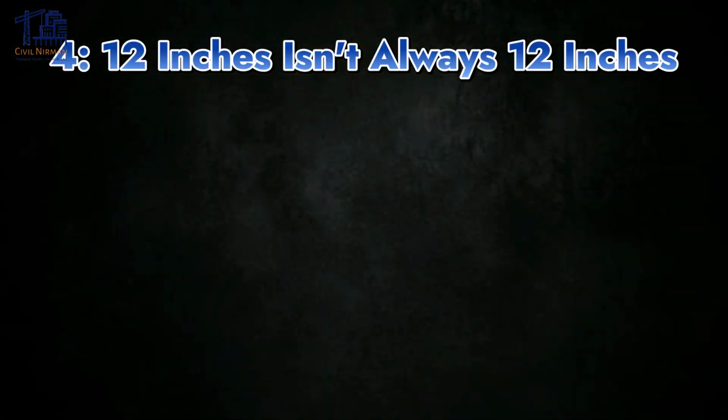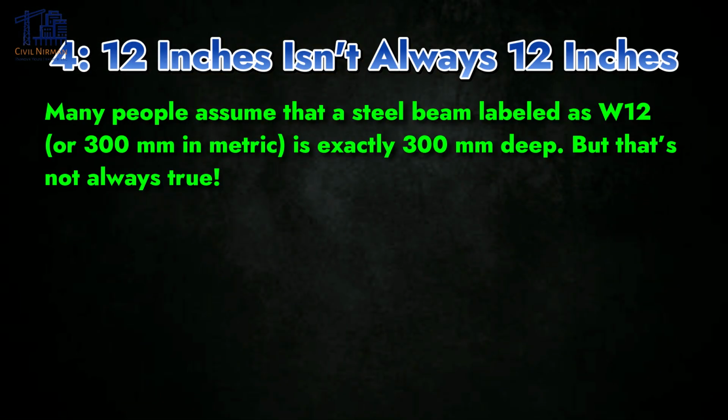Rule number 4. 12 inches isn't always 12 inches. Many people assume that a steel beam labeled as W12, let's say it's 300 mm in metric, is exactly 300 mm deep, but that's not always true.